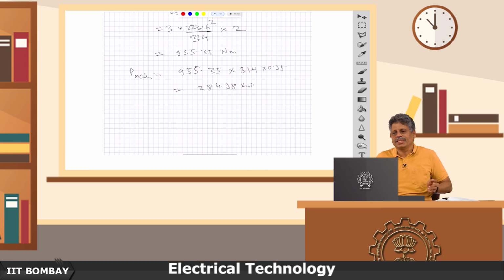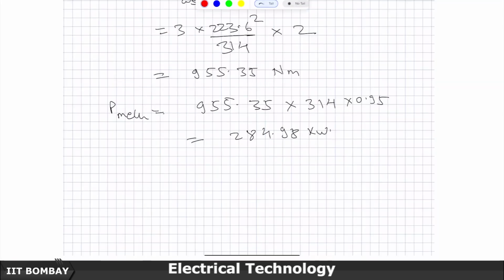So, you can see that if the magnetizing impedance is much larger than the leakage impedances, especially the leakage impedance associated with the stator winding, then the approximate approach can be used to avoid calculation of the Thevenin's equivalent circuit. That is the main takeaway of this example, other than the fact that we also did one solved example.